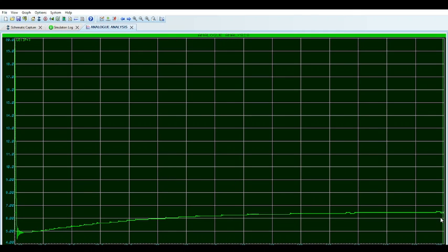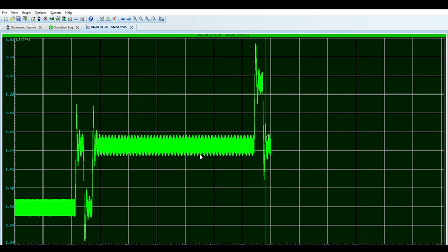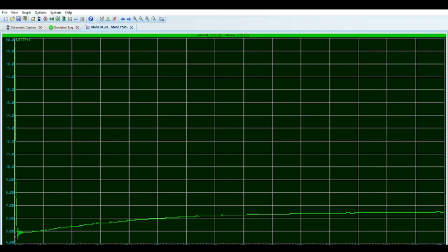And obviously here, it's literally just going to jump from 6 point whatever, that value there, to beneath that, because obviously, again, the PWM resolution is just not there. So you have to be careful and take it easy with it, and it's going to go up and down like that, but it's okay.